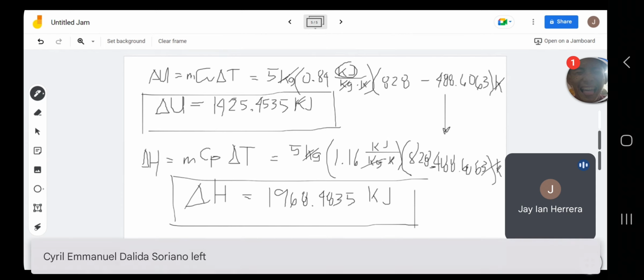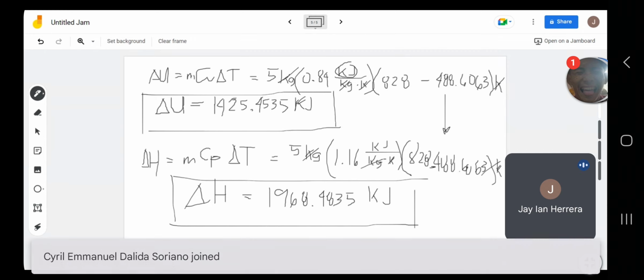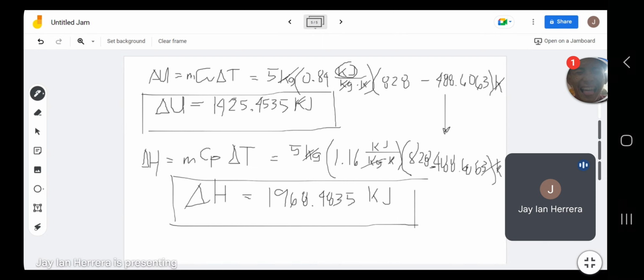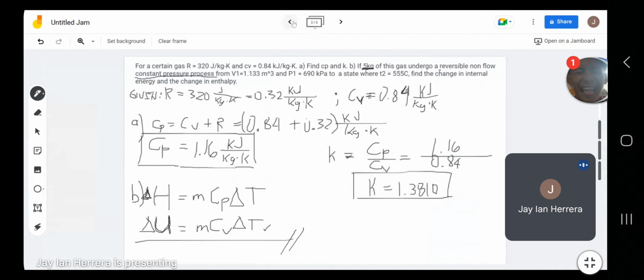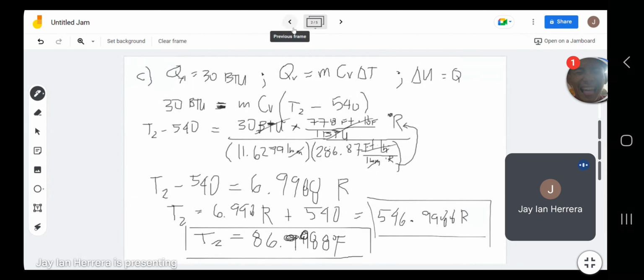We really need to go through this before we get to thermodynamic processes. This is one of the fundamental aspects of thermodynamics, the specific heat. You will still use this up to Thermo 2 and so on. But in Thermo 2, the specific heat ratio is not used much; what you will use there are the specific heats, Cv and Cp. The specific heat ratio is for ideal gas.